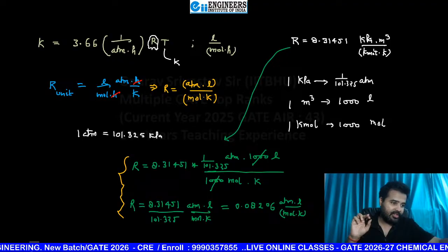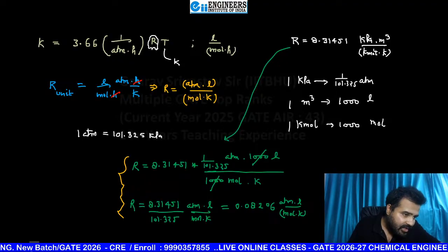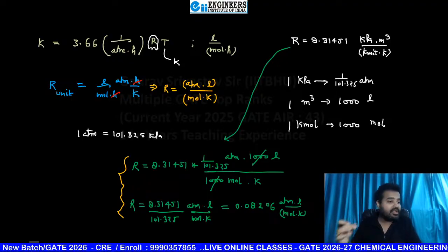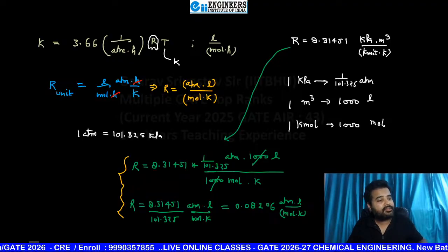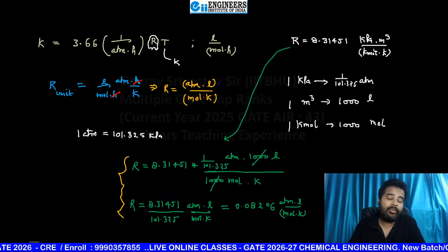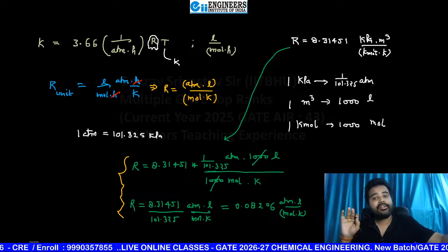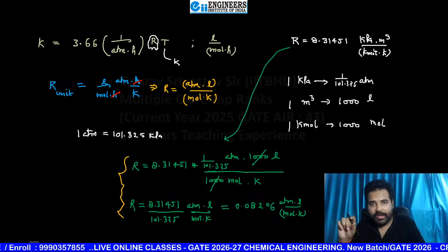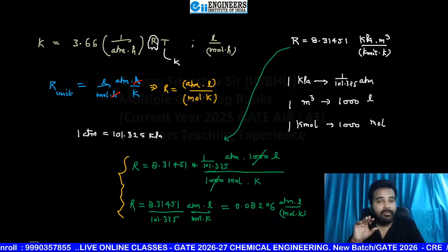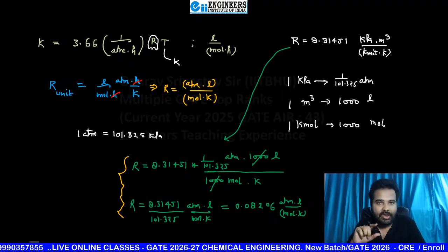Sir, for a gaseous reaction, can we write Na by V equals Ca? Yeah, beta, for gases as well as for liquids. But you must be sure that if a gas is there and the reaction is going on, then whenever you write V, V may be a function of conversion if the expansion coefficient epsilon is not equal to 0.